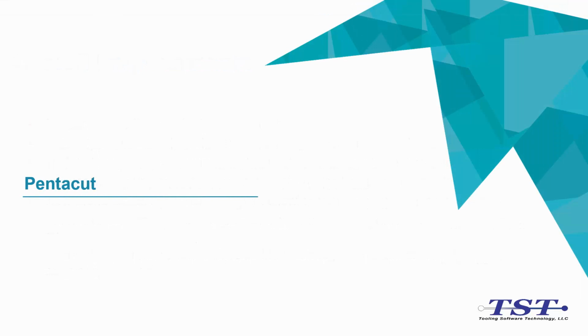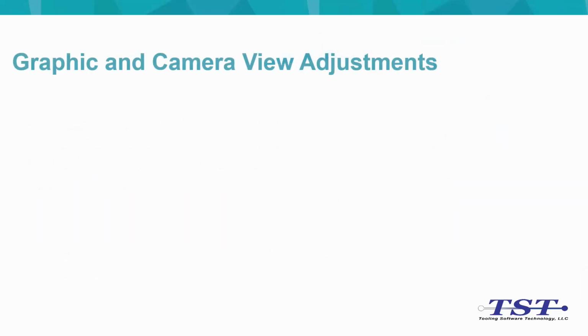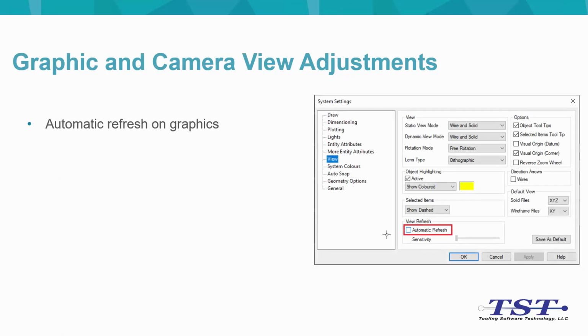For the Pentacut side of the software, there have been a few updates. This includes the graphic and camera view adjustments. There's now an automatic refresh on graphics. As you're zooming in and out, it will attempt to rebuild the graphical display. On older systems, this can actually slow down the PEP system, but within the system settings, you can decide whether you want this turned off or on, as well as the sensitivity of the refresh.